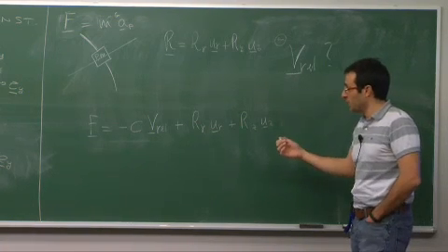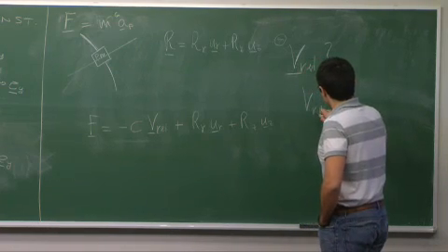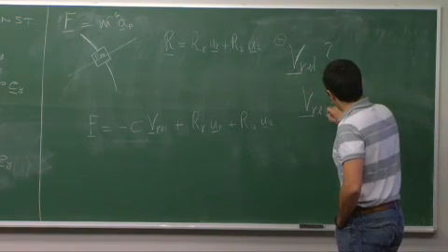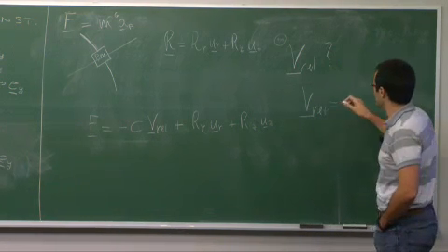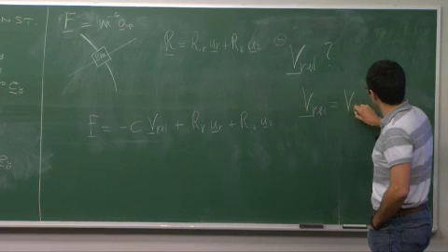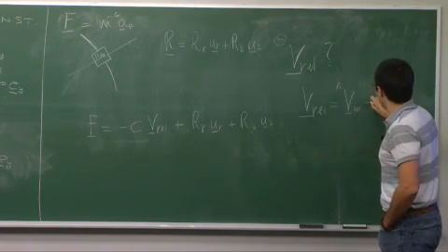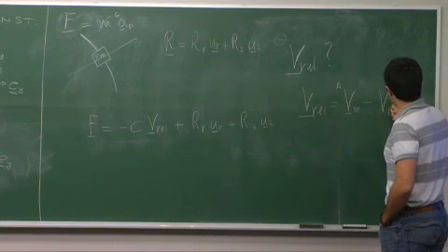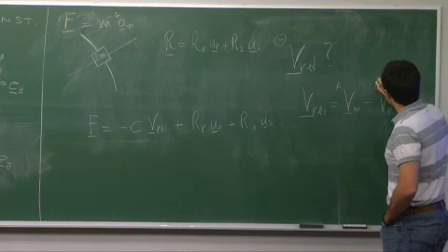Okay, so the relative velocity, that's how we defined it. When we look at a point on a surface, we define the relative velocity, and that point is in contact with the surface, as the velocity of the particle of mass m with respect to any reference frame minus the velocity of the point as belonging to that surface, I think we called it S, in the same reference frame.